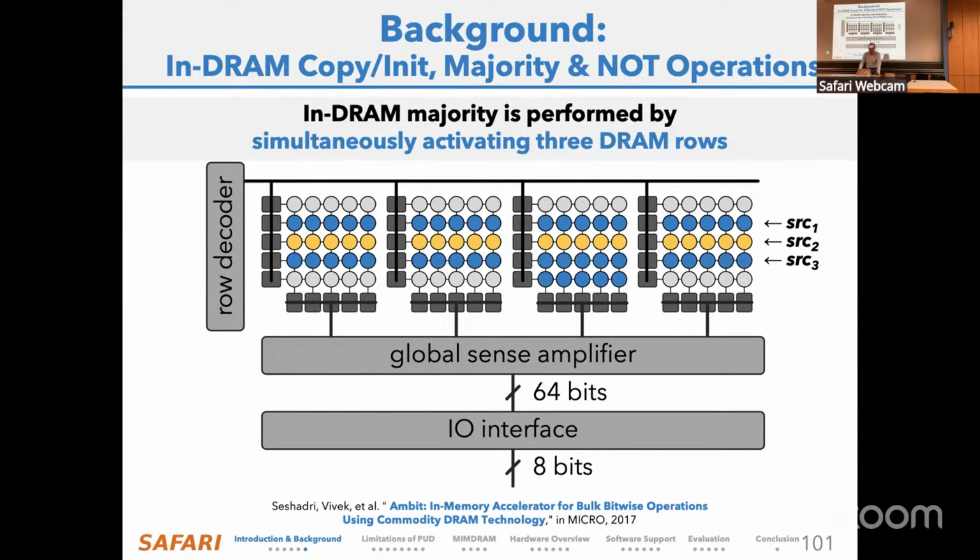It turns out there are multiple what are called mats in DRAM. And the reason is, if you want to activate 8 kilobytes, that's a very long word line. What people do is they have the row decoder connected to the word line, and there is a piece called a mat that is essentially activated through this part.